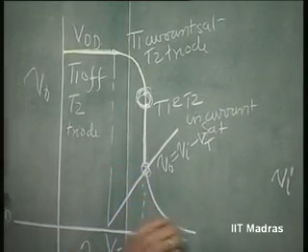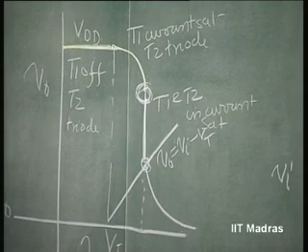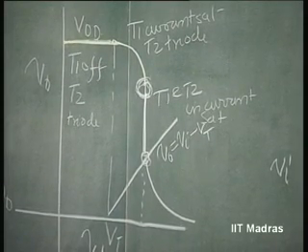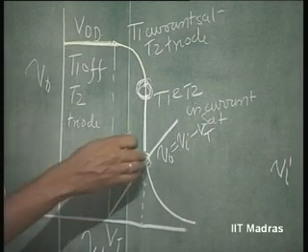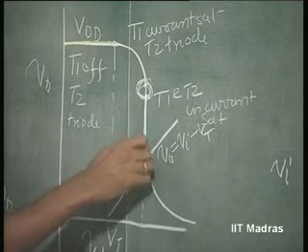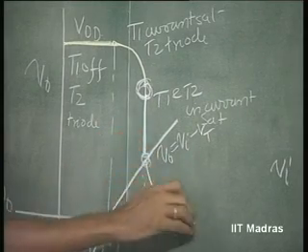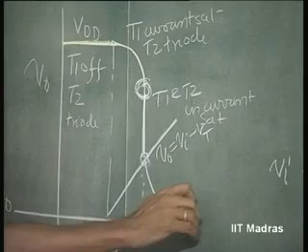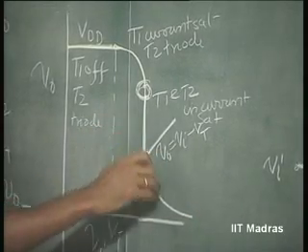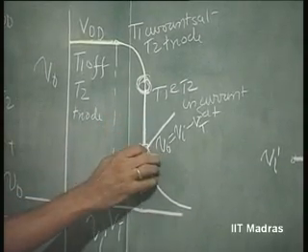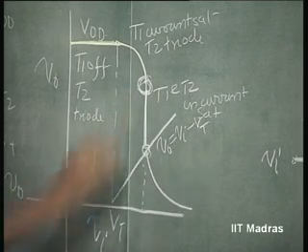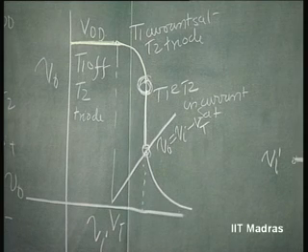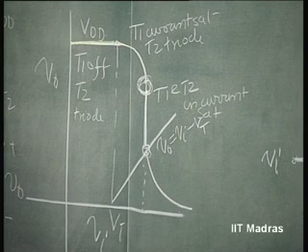Thereafter, of course, we have this. This completes the characteristic of the inverter. I would like you to evaluate the transfer characteristic for this portion, where the entire amplifier is in saturation, equating the T1 current in the triode region to the T2 current in the saturation, that is of course IDSS.